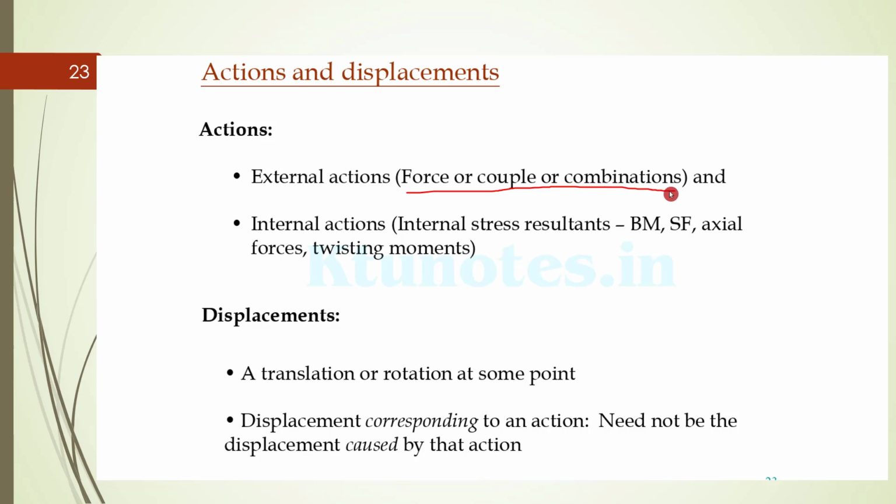So it can be a moment, it can be an axial force, or it can be a combination of force and moment. There can also be internal actions, which are the resultant to this external action, called stress resultants: the bending moment, shear force, axial force, twisting moment, which will happen due to the actions of the external force.